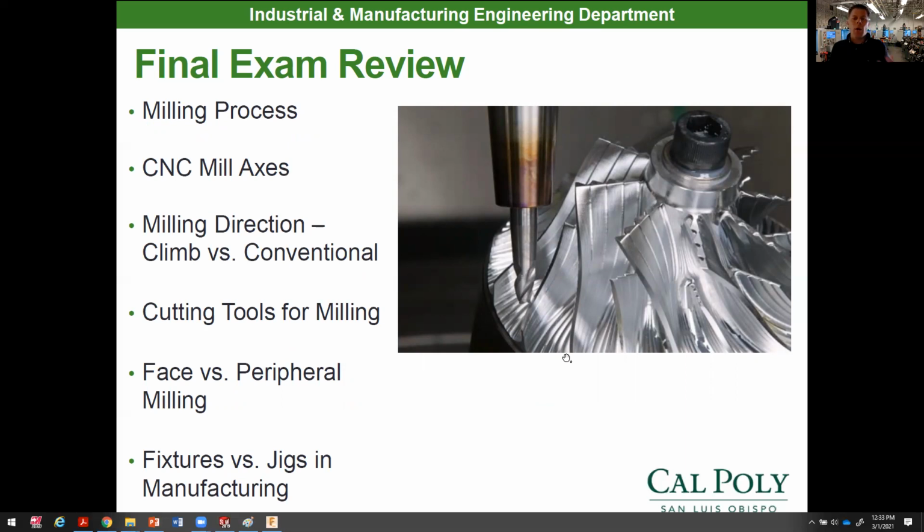So once we saw our workpiece up into a blank, we have milling processes that occur. And I would understand the process of milling. I'd be able to define what milling is, know that it's got a multi-tooth cutting tool that rotates to basically feed material past that multi-tooth cutting tool to make prismatic looking parts. So milling is a process. Milling is performed on a machine tool called a mill, and the standard CNC mills have 3 axes of linear motion right there, X, Y, and Z.